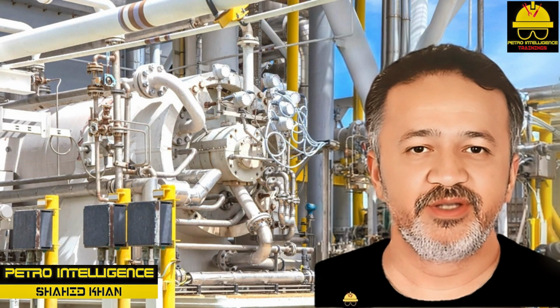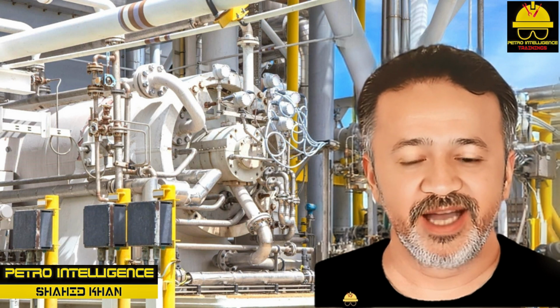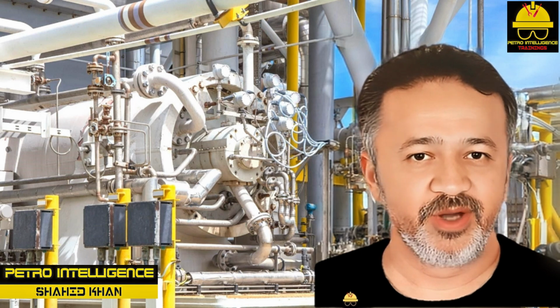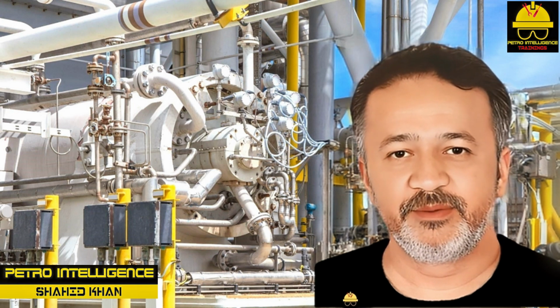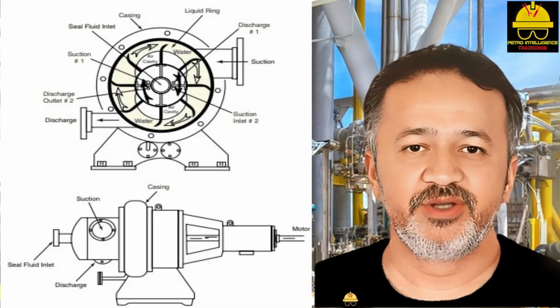Liquid ring compressors. A very unusual compressor design is the liquid ring compressor. It combines the centrifugal action of the liquid with a positive displacement, rotary action. A liquid ring compressor has one moving transfer element and a casing that is filled with makeup water or seal liquid as shown in picture.